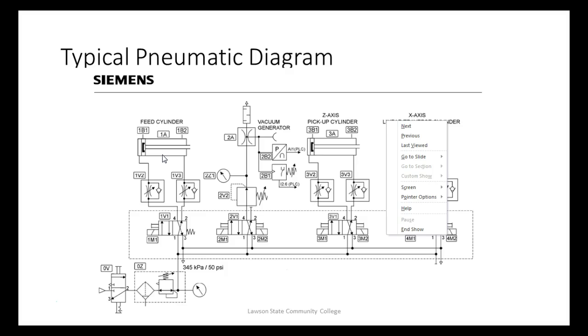Plus, the longer you get that rod out there, the more tendency it's going to have to bend on you, right? You understand? Because you're trying to generate force with a rod that's sticking out there. So if you look at your jack, if you got a hydraulic jack, it's got a real big rod on it, but it only extends out that far, right? If we was to take that and put it up 4 feet, then odds are it would bend trying to lift the car. So what's nice about a rodless cylinder, basically the only thing that limits the stroke on a rodless cylinder is how far your cylinder goes. And plus another thing, if you need a 12-inch stroke, then you're going to almost occupy only about what? 12 inches of space.